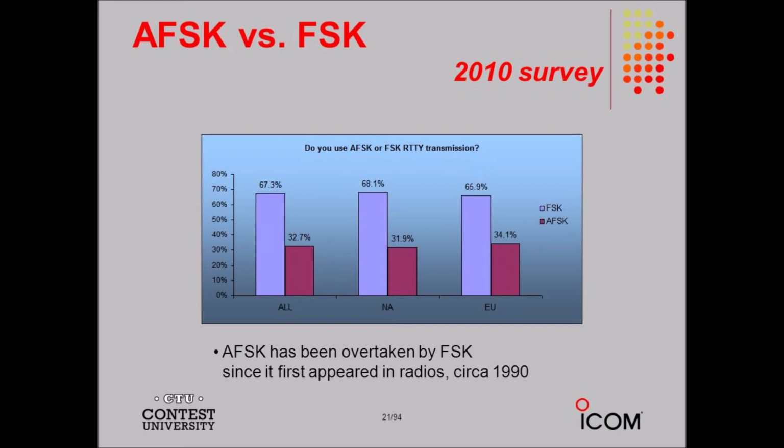Basic SSB transmitter. Figure 25.6 is a block diagram of a simple SSB transmitter. The RF amplifiers that follow any type of amplitude modulator, including a balanced modulator, must all operate in a linear manner to prevent distortion and unnecessary spreading of the signal bandwidth, a condition that some engineers and radio operators call splatter.